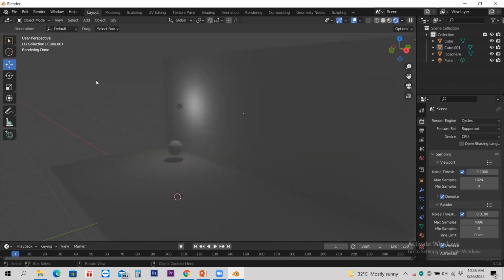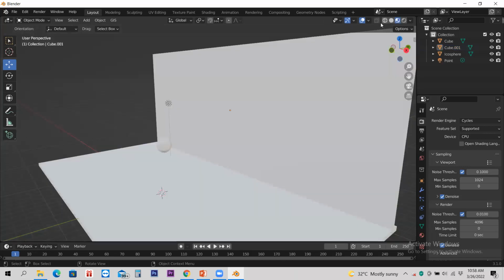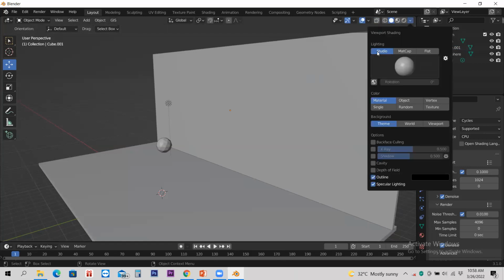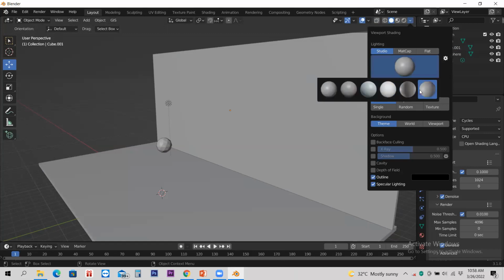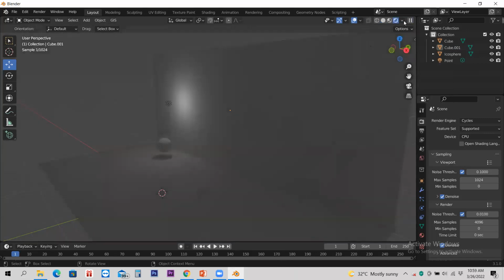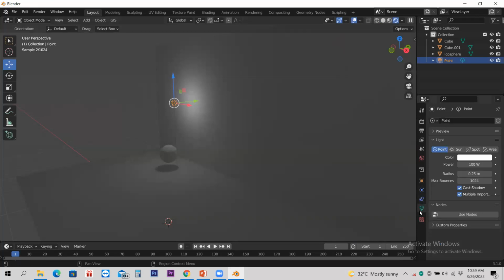Okay. I think it has nothing to do with that. In this tab we are talking about, we can go to this studio here, and here we can change it. But in the rendering tab, this is a lighting simulation, so it doesn't affect anything. If it is not coming, just for the time being click this light and increase the power.